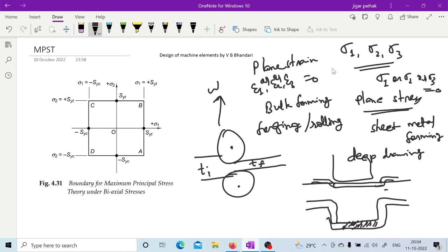In punching, the sheet metal punching that you have drawn, there is a shear stress at the ends, isn't it? It will be through that shear. When in case of deep drawing, you will not have any shear, I guess. It is biaxial stretching in case of deep drawing. Shearing will be there when you go for blanking. In blanking operations, you will cut your material through that shear. In case of deep drawing, it is biaxial stretching.